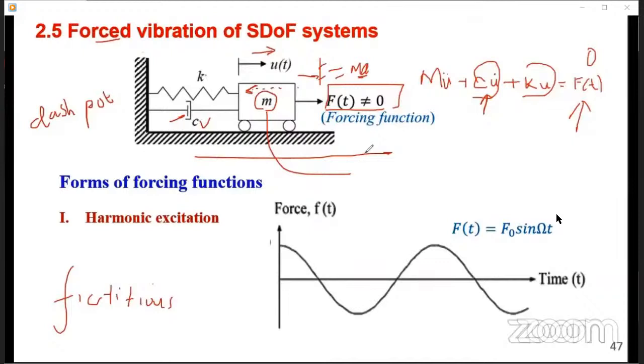So we are saying the forcing function, the harmonic forcing function, not harmonic. I'm just taking you back to lesson number 1, where we talked of the different types of dynamic loads, because this is what we are talking of this year. This is now our point of interest, the forcing function, the external force, for it to be a forced vibration. Now, this force we talked of as deterministic or stochastic. Deterministic loads can be expressed as a function of time, so you can predetermine them. But stochastic are random. And we gave an example of earthquake loading.